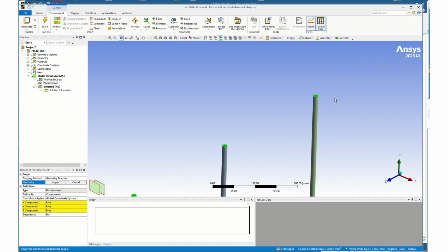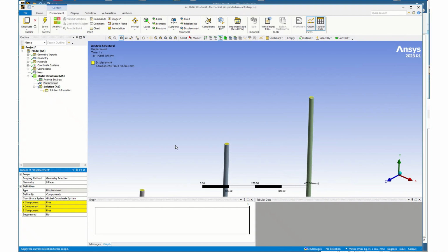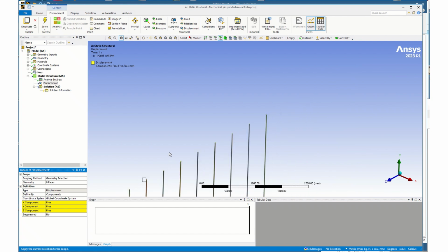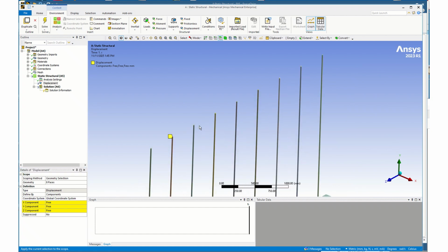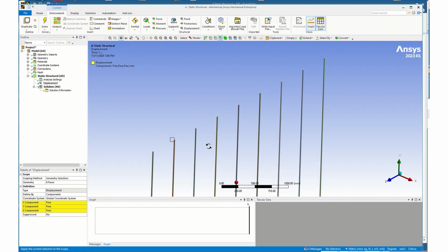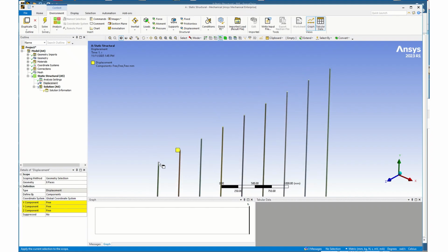To make sure you got them all, when you come over here and click apply, you should see that there are 9 faces. I only have 8, so I need to go ahead and see which one I missed, and it looks like it was this very first one. So I'll rotate those, and I will pick these faces again. I'm on face select.